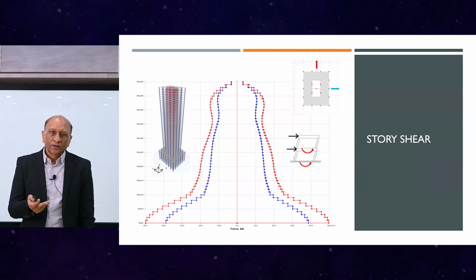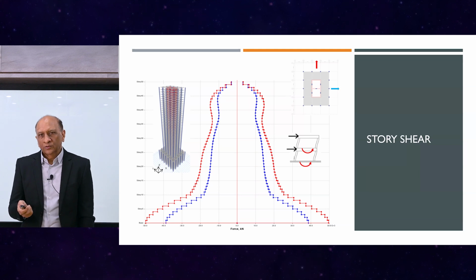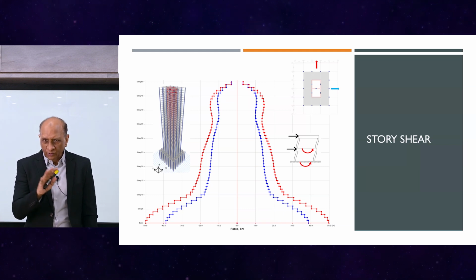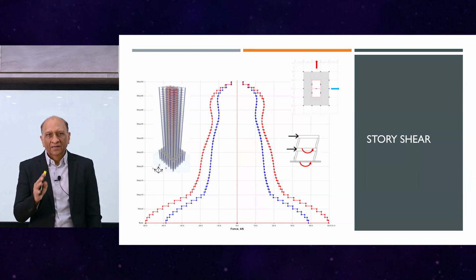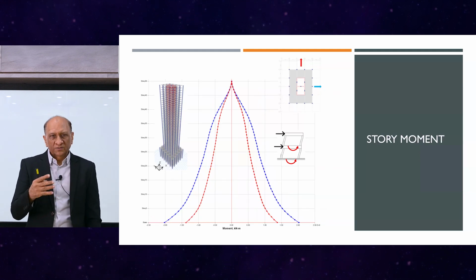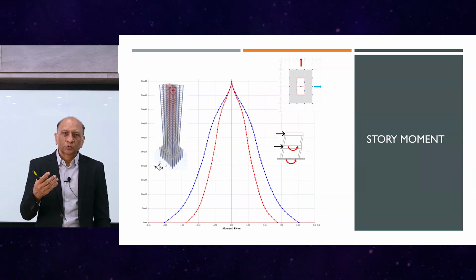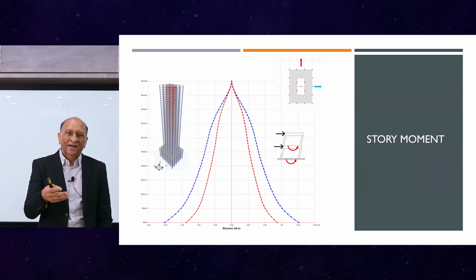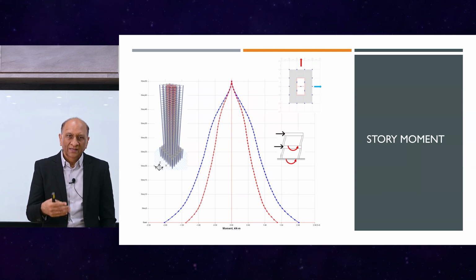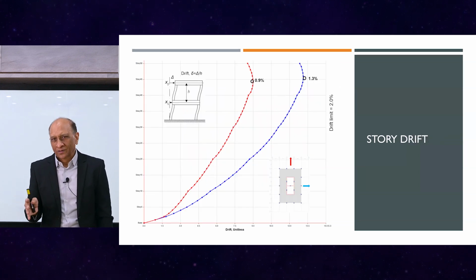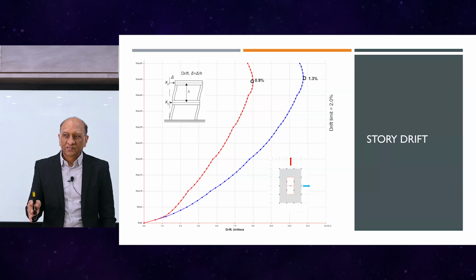So how that is done is through the codes. And this is the ACI 318-19 formulas. You have 3 groups of formulas here. Left-hand side is the general approach, it's constant numbers which you need to check. For the walls, there is a range for uncracked and cracked. If it's cracked, you need to come back and modify again. So you run it twice. And there is a general formula that you just use 0.5 Ig. If you are lazy and don't want to do anything, then we can just go ahead with that.